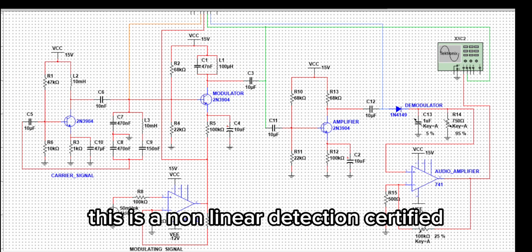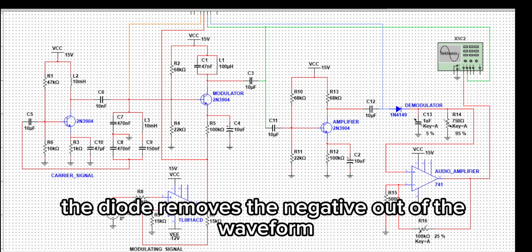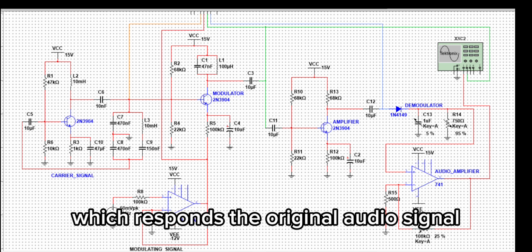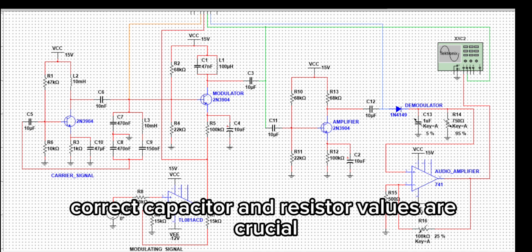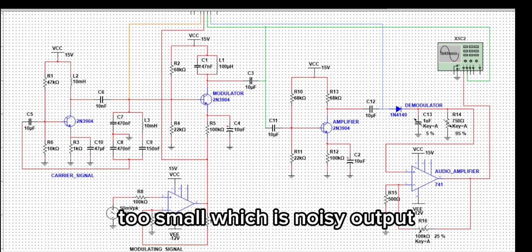This is a nonlinear detection circuit. The diode removes the negative half of the waveform, while the RC network extracts the envelope, which corresponds to the original audio signal. Correct capacitor and resistor values are crucial. Too large gives distorted audio. Too small gives noisy output.